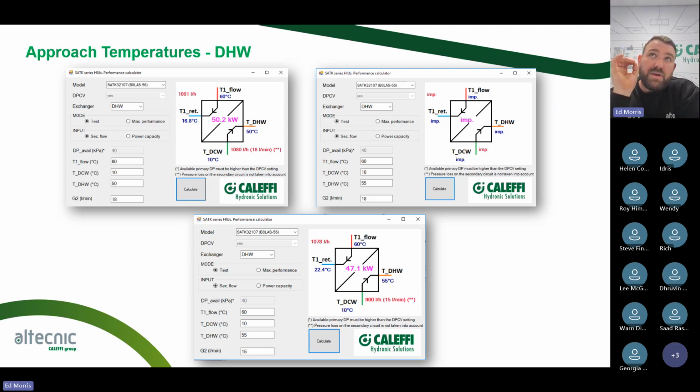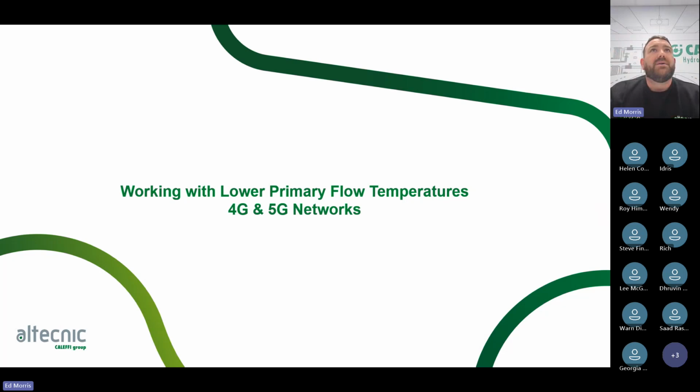On a simulation tool, if the HIU can't perform to what you're trying to achieve, we can't give you a calculation. So it's really important that we get the correct information when it comes to sizing it, or trying to run some simulations to make sure you're getting what you can. And all that will identify your flow rates through your primaries, and your flow rate through your hot water for your outlet. So you get 15 litres a minute, 18 litres a minute, whatever it may be. We can optimise that and we can tailor that to how it needs to suit your system essentially.